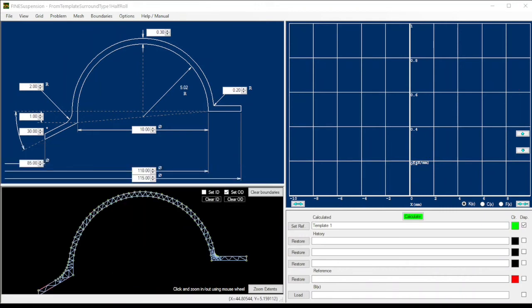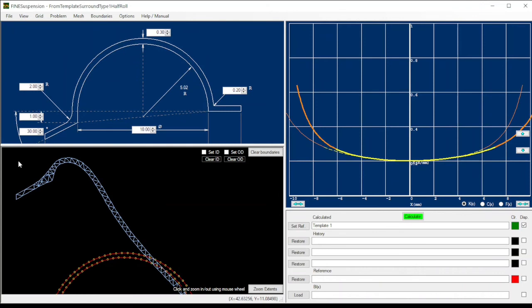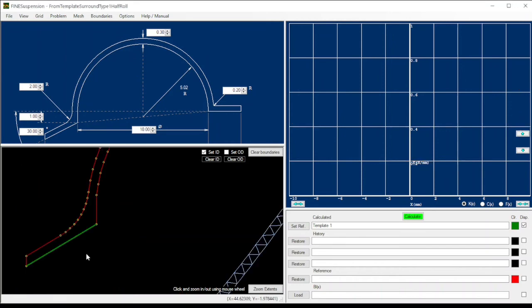First, we may decrease this overhang here to 0.2 millimeters. Zooming in, we notice that the surround flange actually is bending slightly at maximum excursion. Assuming the cone edge is stiff, we may fix the upper side of this flange, like here.